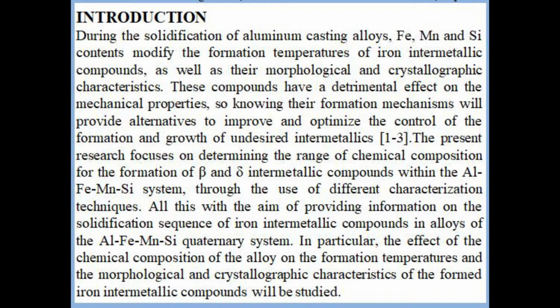The present research focuses on determining the range of chemical composition for the formation of beta and delta intermetallic compounds within the aluminum, iron, manganese, silicon system through the use of different characterization techniques. All this with the aim of providing information on the solidification sequence of iron intermetallic compounds in alloys of the aluminum, iron, manganese, silicon quaternary system.